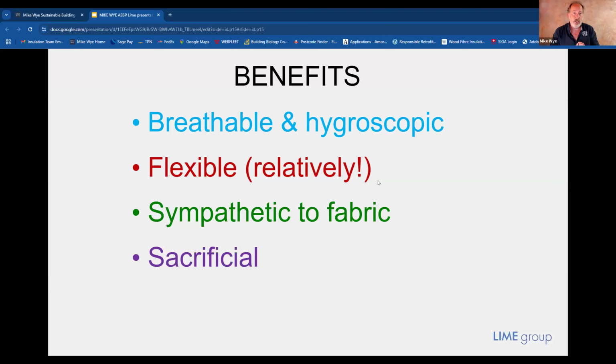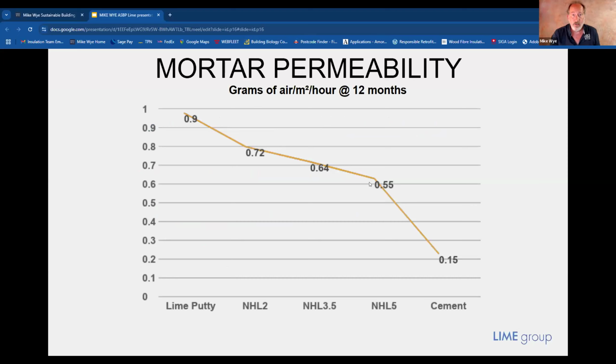This can have serious issues to do with freeze-thaw damage and spalling of brick or stone during the winter time, when we have saturation at the surface and ice crystals forming and causing the material to become weaker and weaker. And also, if we have a lot of moisture moving through the brick or stone, it can bring with it salts, which will then evaporate, or the moisture content evaporates near the surface. The salts will then crystallize, and similar to the formation of ice crystals, it can be quite damaging to the fabric of the building.